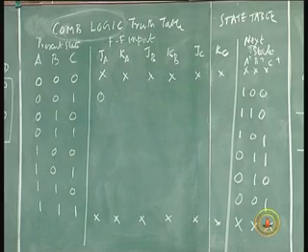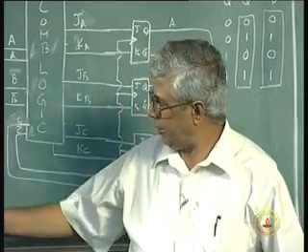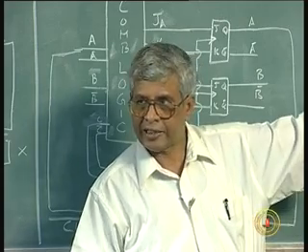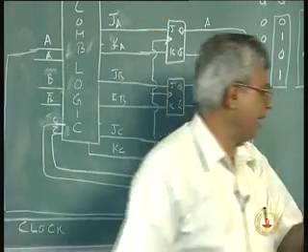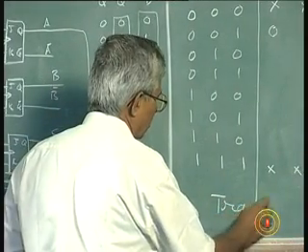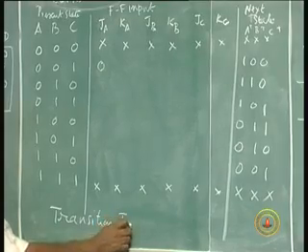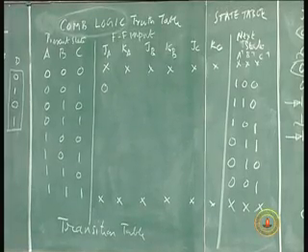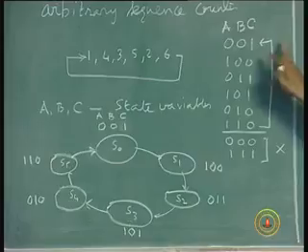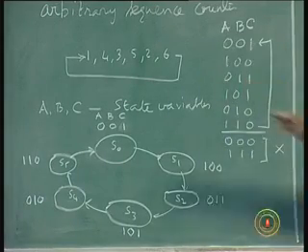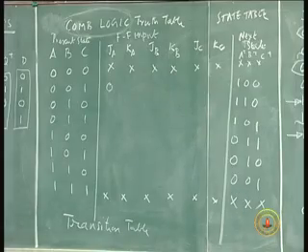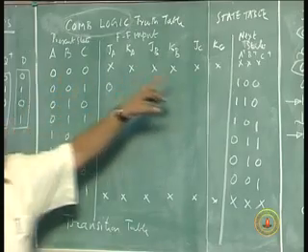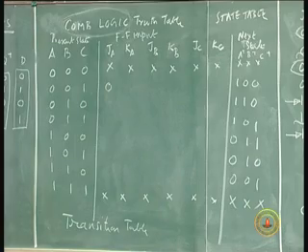This table is not called a state table, it is simply the state to state variation. This is the state graph or state map. If I write a table for this instead of a diagram, present state 0 0 1, next state is 1 0 0, present state is 1 0 0, next state is 0 1 1, that is, instead of writing a map or graph, I write a table, such a table is called a state table. A table which contains not only the state changes, but also the inputs of the flip flops, such a table is called a transition table.